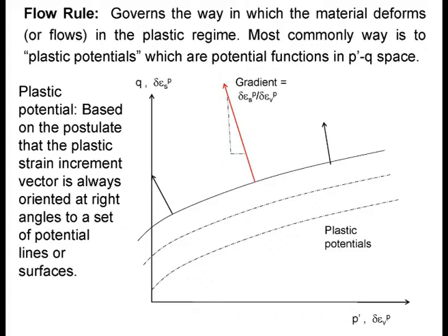Now, at this point, a lot of things are still unknown. For example, what is this shear strain? Because this is not the normal shear strain. I will define the shear strain when I come to Mohr-Coulomb in a short while, later on today. But volumetric strain, you probably know. The superscript P there is for plastic behavior. So this is, in a sense, what the framework of the flow rule looks like.